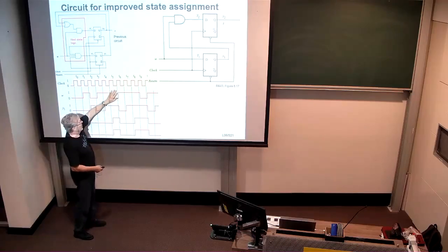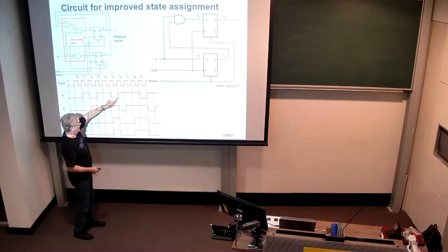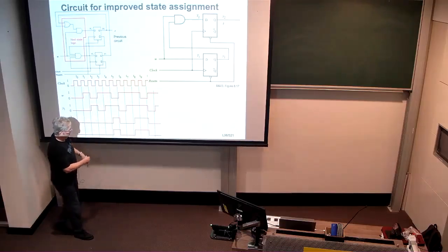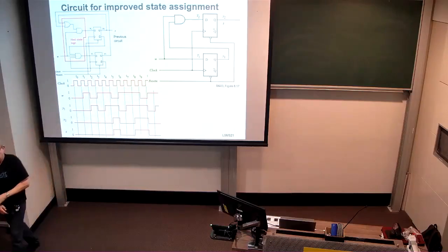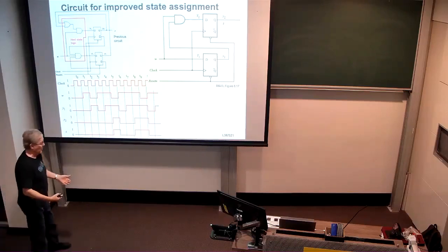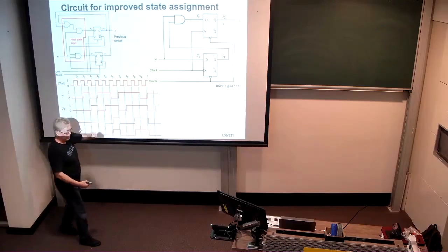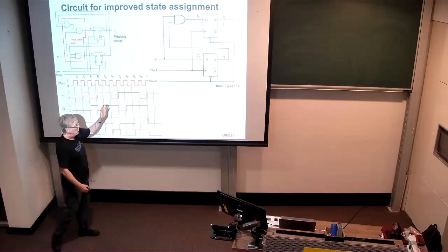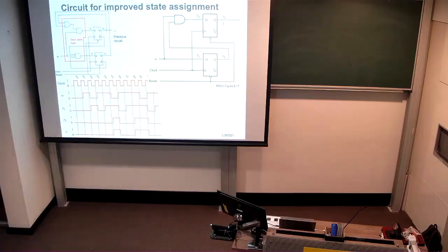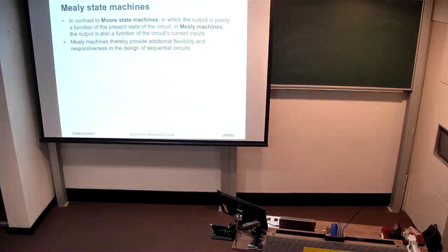But on the next rising clock edge, W is back to 0, so we clear both flip-flops and the output Z. Of course, you need to check that the system behaves correctly for a single W as well, not just two W's, and we also need to check what happens if you get more than two W's in a row to make sure that it's all working correctly.